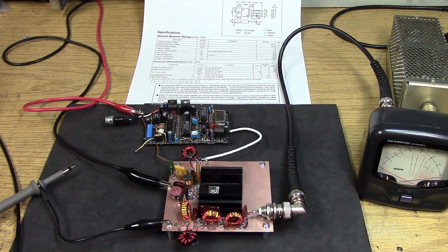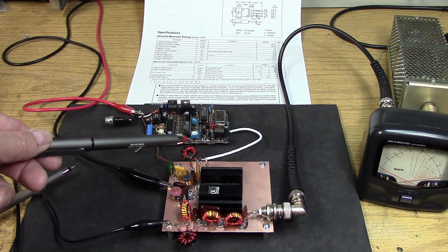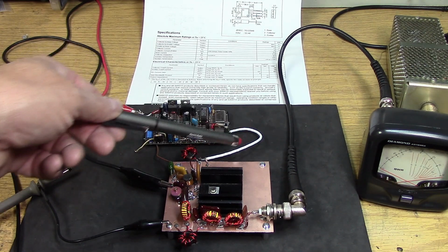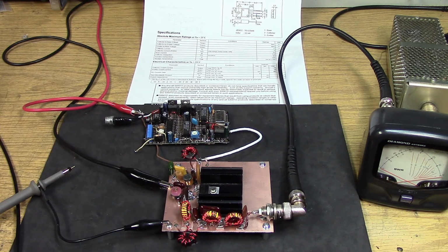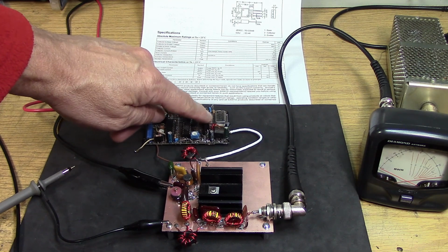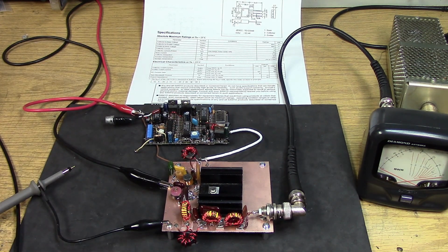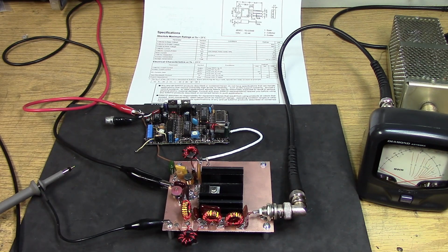So as a precaution, the first thing that I've done with this particular circuit, which looks a little bit complicated to you guys, so I'll go through it slowly, is I've got a 4-to-1 transformer right up front. In other words, we're coming in at 50 ohms, let's say. It's going to transform that down to around 12 ohms. That's just a safety thing, because if you try to drive a really low load, you're going to pop these two FETs on the driver. So we do have to do some impedance matching in order to go into the very low input impedance of the bipolar transistor.